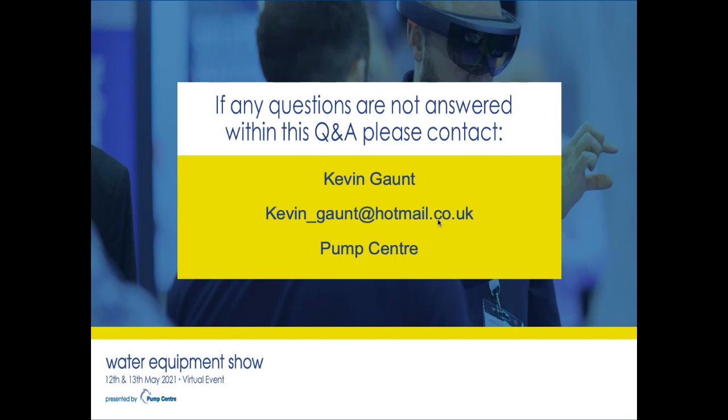Just need quick answers for the next question. What are the considerations for maintaining pumping stations which are infrequently, if rarely, operated but are critical, e.g. flood protection, stormwater, etc.? That's a classic problem that the Environment Agency have, that a lot of their installations are not visited and used very often. If something is really critical, you have to ask the question, perhaps we should visit it more often.